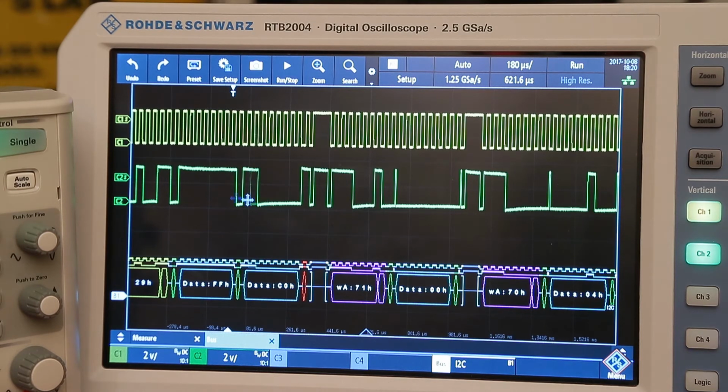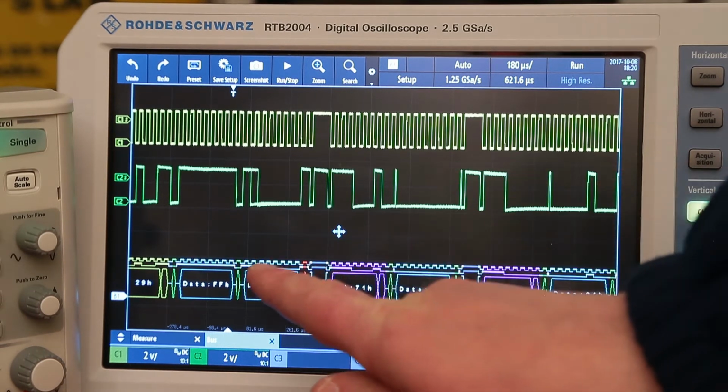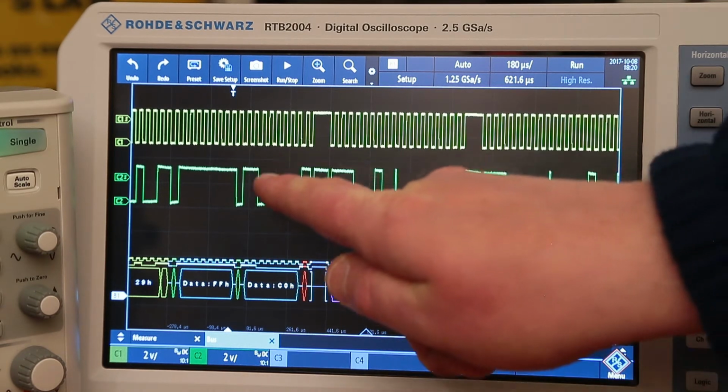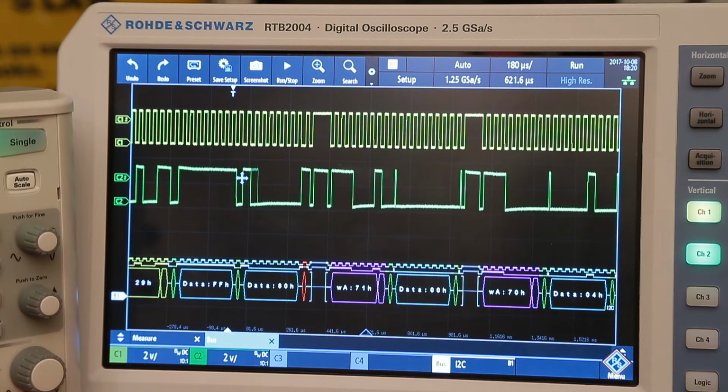I've got the same sort of amount of data. What is also nice on this screen is the bit display, which you can turn off. So above the decode data you've actually got the bits, which are the same representation as the green. So you can actually see this green one that's changing here, which is the bit data that's changing from C0 to 80, and you can see that bit where I'm circling around there flashing, and that small bit representation is changing.